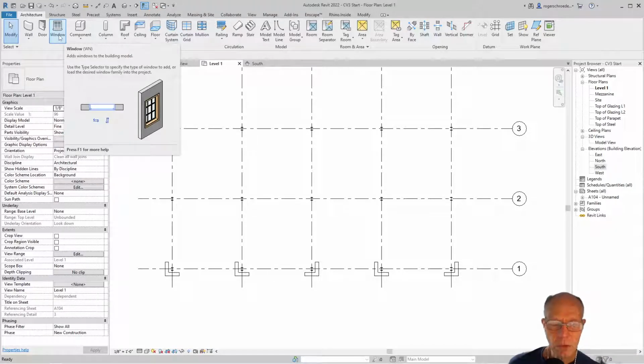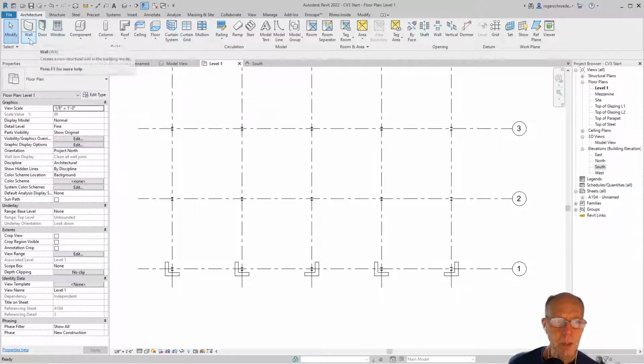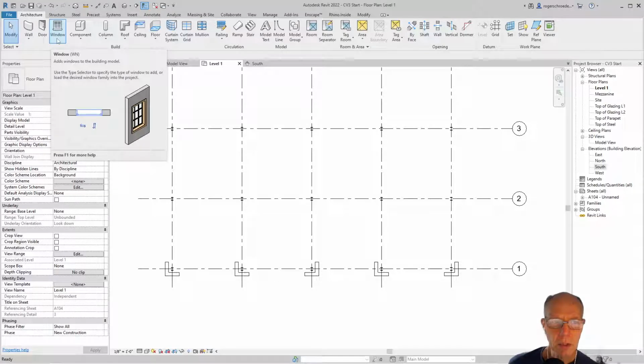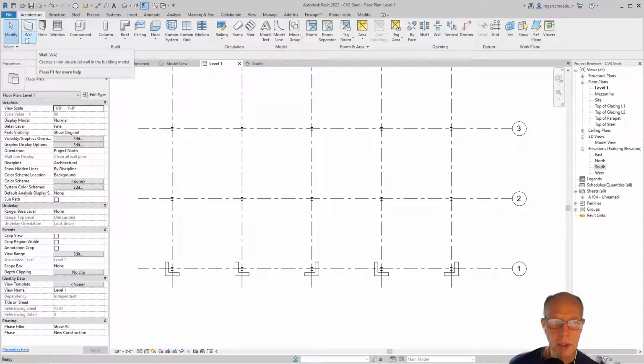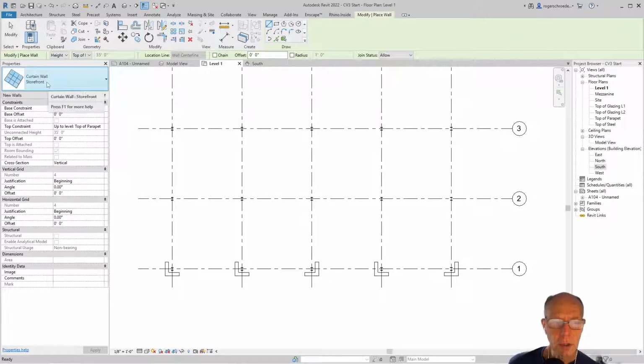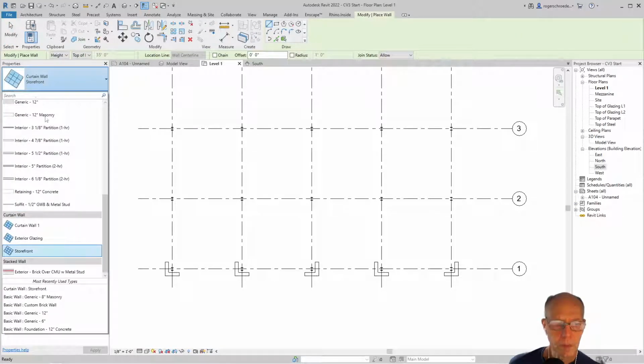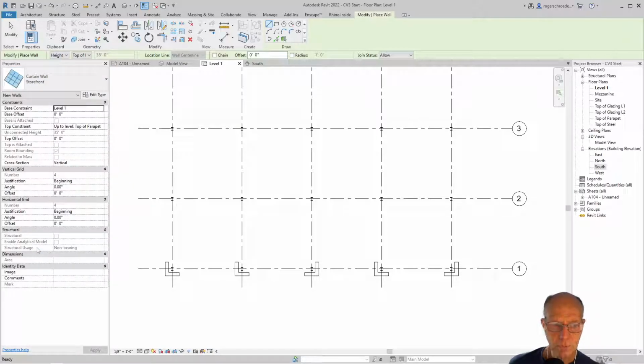It's considered a wall structure in Revit and a lot of BIM modelers. And I want you to remember that, because on one of our check drawings, that's going to come up as a question to you if you're not familiar with that idea of finding storefront glazing underneath the wall tool. And I've already selected it. It's all the way down, past curtain wall, to storefront.